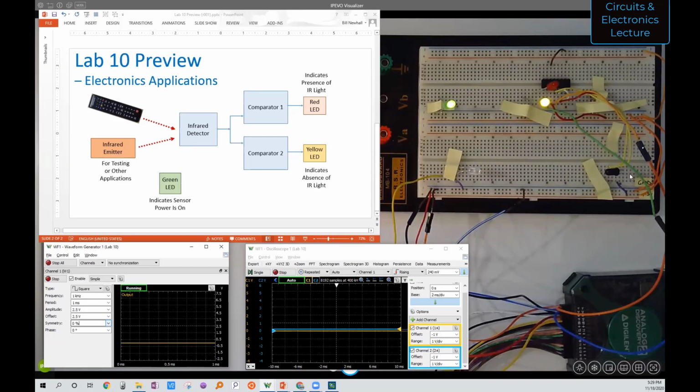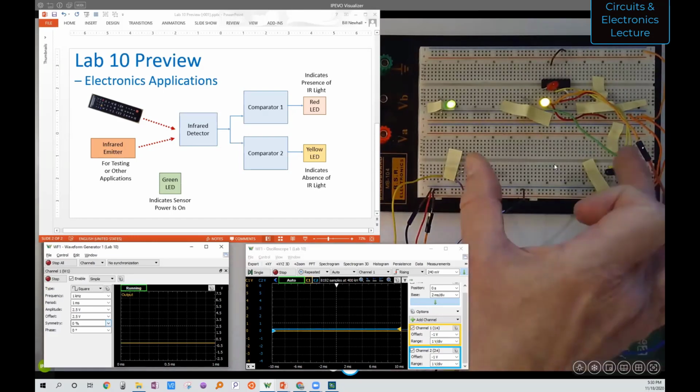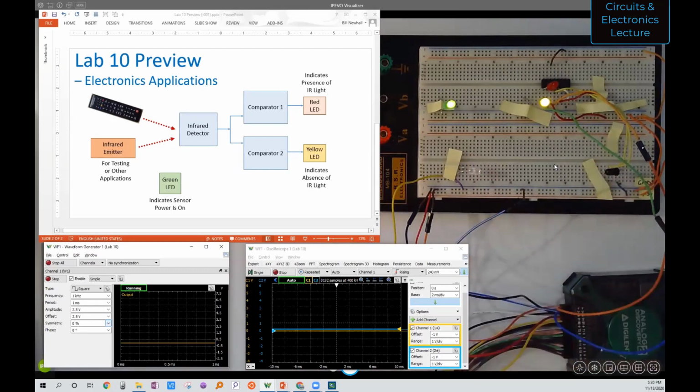So you've done that. You come over here on the right, this is the infrared photo transistor. So this is the detector right here. And again, I will give you some guidance on how to use this. And there's maybe 3-4 inches separating these two. So light's being emitted on this side, it's being detected over on this side, and it's producing an analog signal, and I'll show you that on the scope down here.